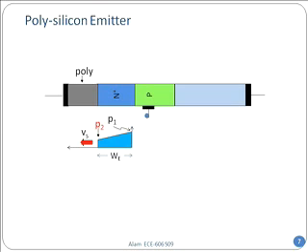If I had a metal contact, then I know that P2, which is the other end, the concentration should have been 0. What polysilicon does is that it limits the velocity at which electrons can go. So it's like a surface recombination velocity, and it is not infinite, unlike metal. As a result, because it has finite Vs, the P sub 2, which is on the other end at the polysilicon junction, is not 0.